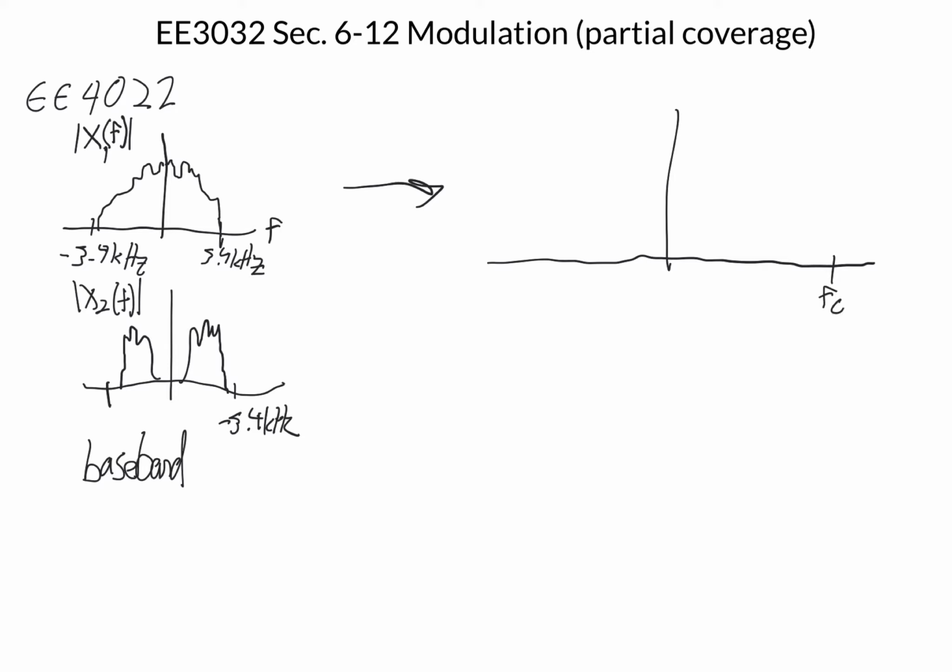our medium can support, called a carrier frequency. For radio, this might be, as I said, in the high kilohertz or low megahertz range. If we're using the ISM bands that 2.4 gigahertz Wi-Fi works in, this might be somewhere around 2.4 gigahertz. And we take that Fourier domain signal and we move it up so that it is centered not at 0, but at this high frequency.